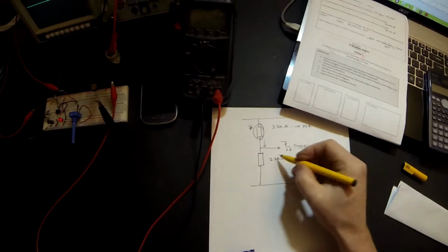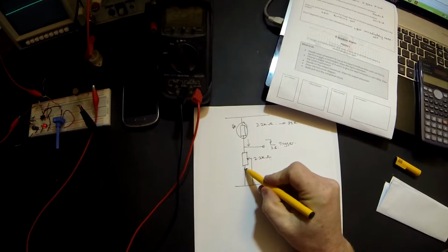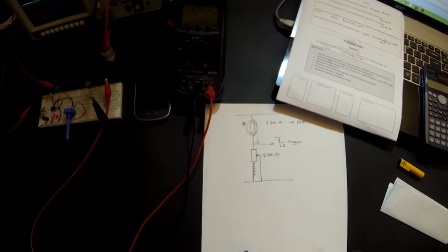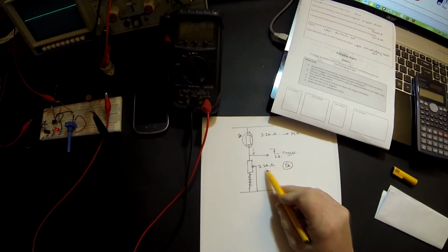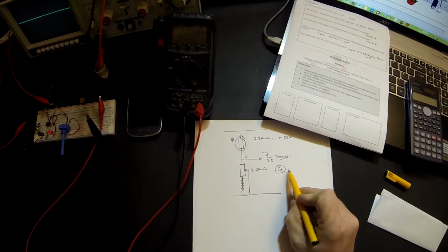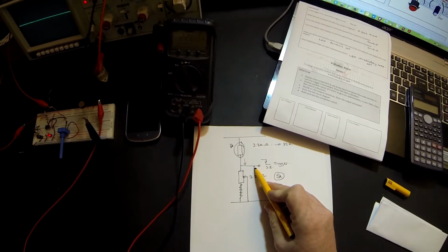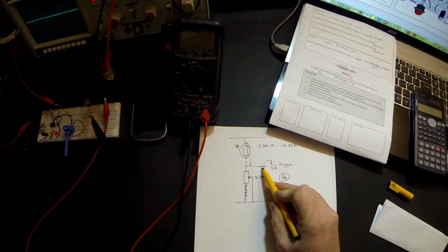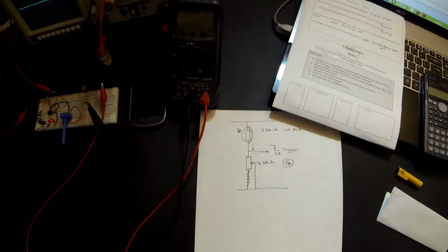So the best way to do this is actually to put in a variable resistor that covers the range that we want. So we're going to be using it as a variable resistor and not as a potentiometer, so we're going to be using the middle leg and an outside one. So why don't we try a 5k resistor? A variable resistor, so we can adjust this between 0 and 5k. When it's 0 ohms, then of course this voltage will be 0, and when it's higher it will certainly be above the 2.5 volts because it's greater than the 2.2k.